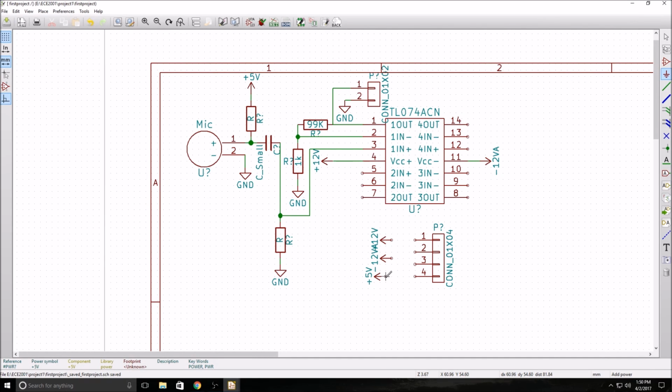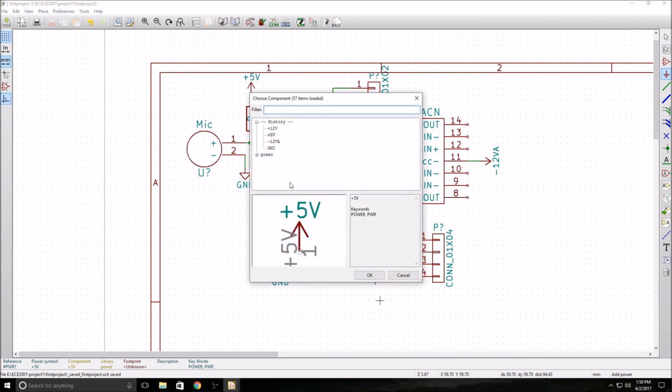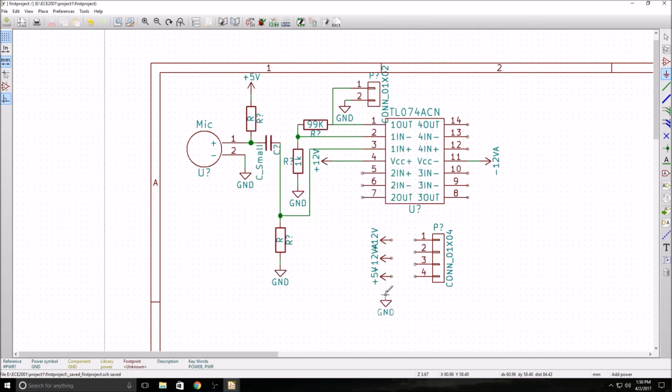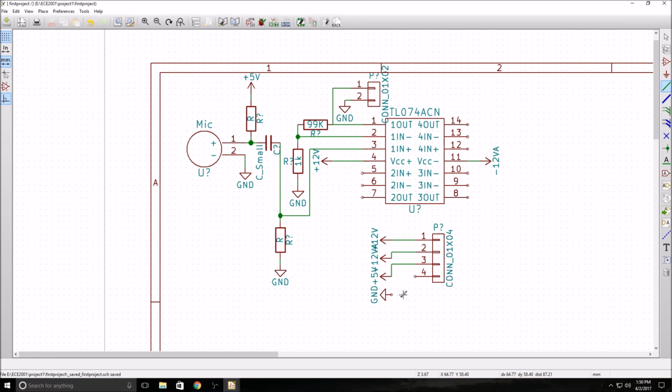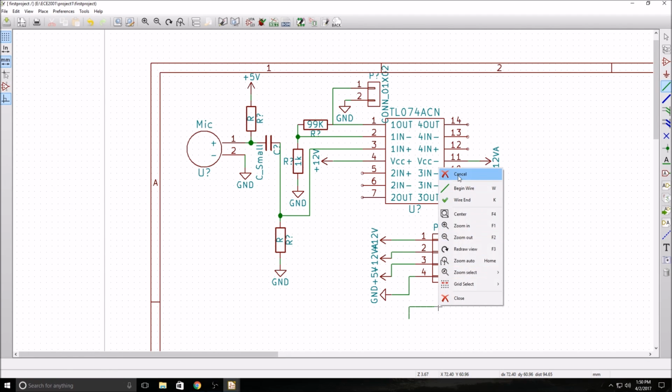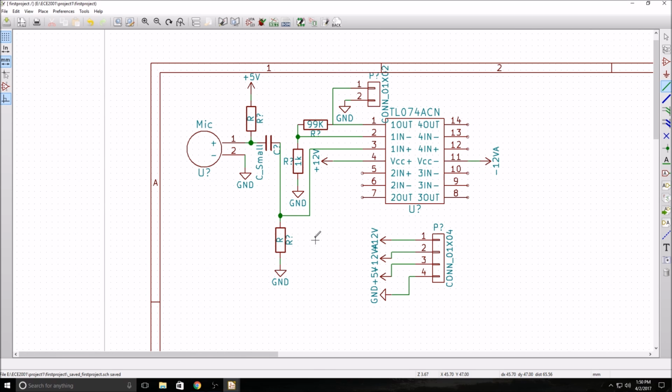Now this order, depending on how you do this, again, these pins are what are physically going to be the connecting point for each one of these guys, so you need to keep that in mind. Cancel. Whoops, cancel that. We'll just wire these across like so. So on pin 1 of this strip will be 12 volts, and then on pin 4 will be ground, so that's the one that you want. So now we have our basic component completed, our basic schematic completed.